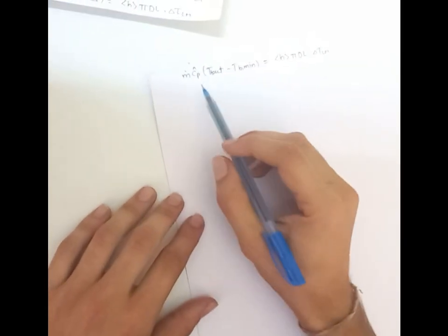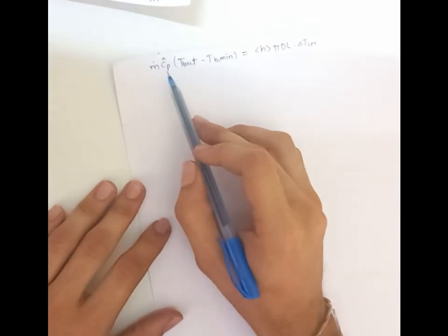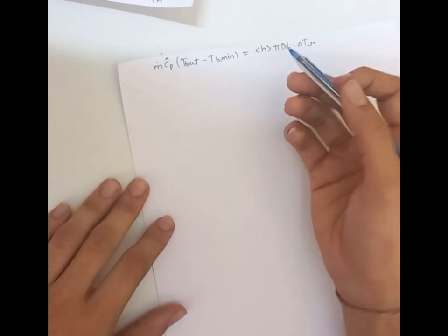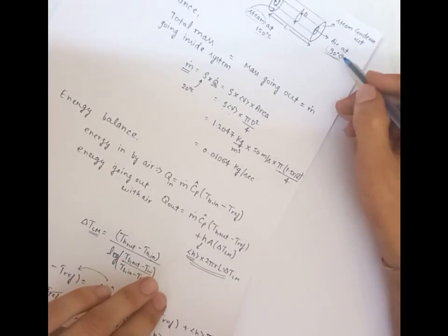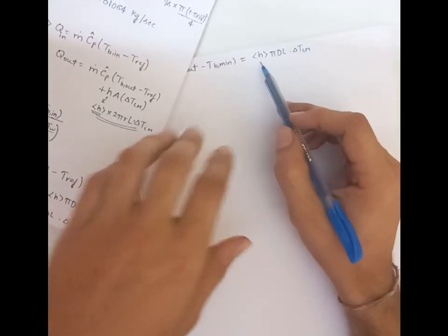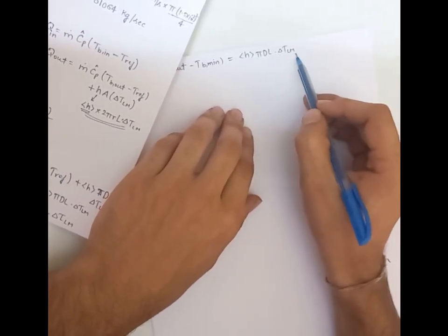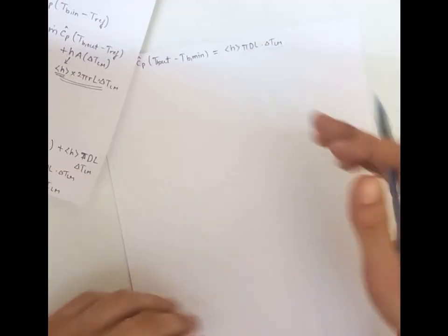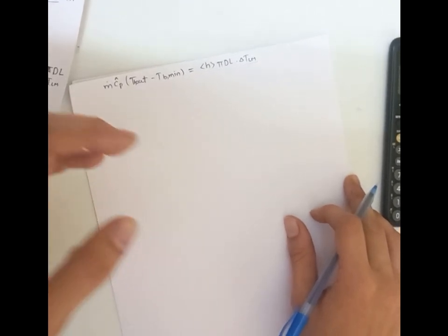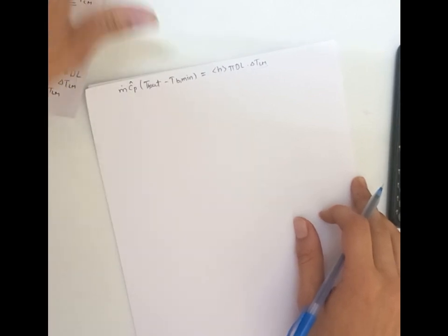So now at the end of the energy balance, we get this relation, that is mass flow rate, heat capacity, and the TB out, that is the outlet temperature of the air. In this case, it is 90 degrees Celsius, and the input temperature is 20 degrees Celsius, and H, the heat transfer coefficient, and that area, and the logarithmic mean of the temperature difference in the heat exchanger. So now we're going to substitute the values here and proceed with the solution to find out L, that is the length of the heat exchanger.